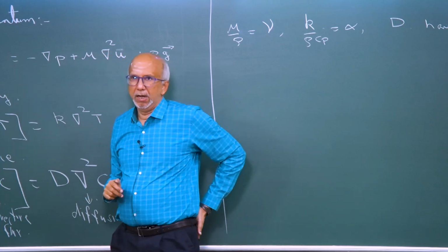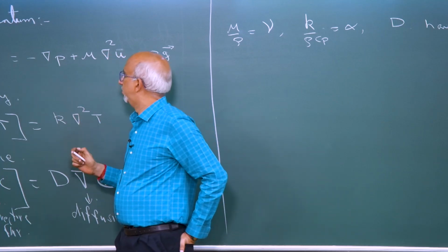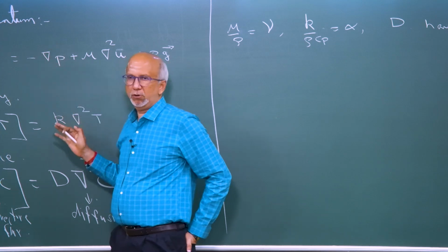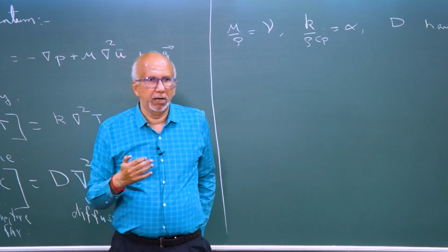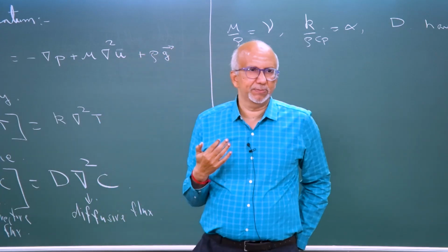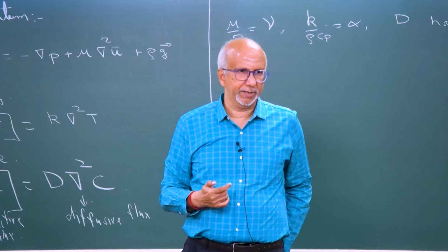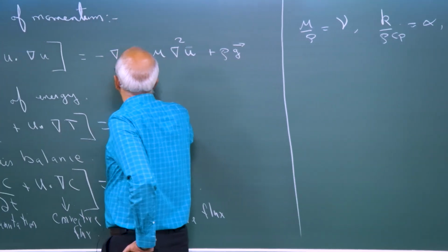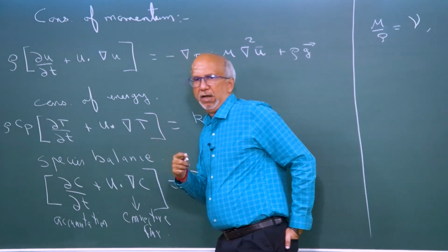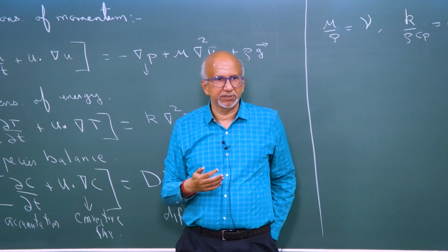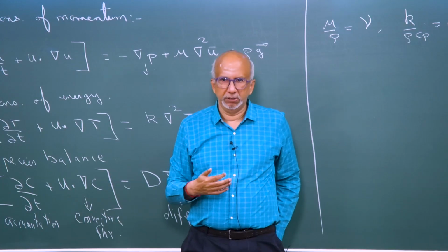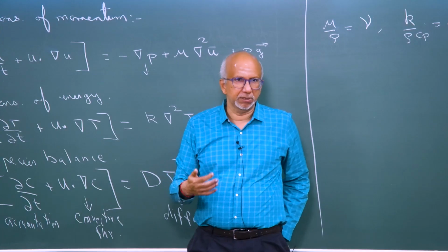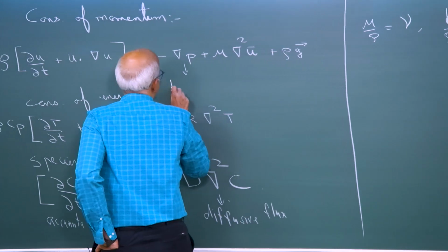Now, in this particular problem, you might see this equation with some extra terms sometimes, okay. For example, this is the pressure gradient, the pressure difference which drives the flow. If there is no pressure gradient, the flow is not going to take place. So, this is like a source term, okay.